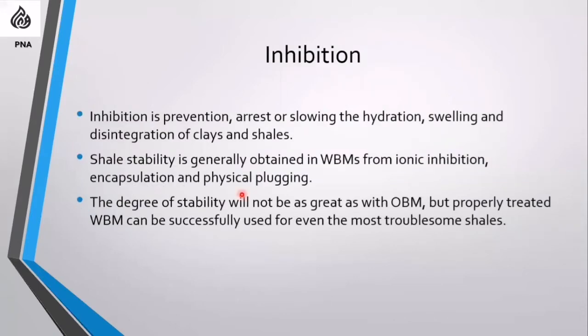Inhibition, as a definition, is the prevention, arrest, or slowing of the hydration, swelling, and disintegration of clays and shales. Shale stability is generally obtained in water-based mud from many mechanisms such as ionic inhibition, encapsulation, and physical plugging.